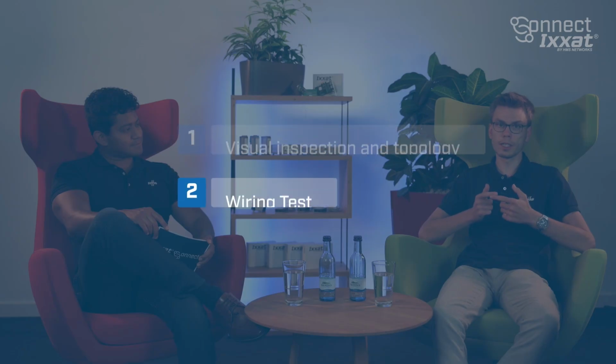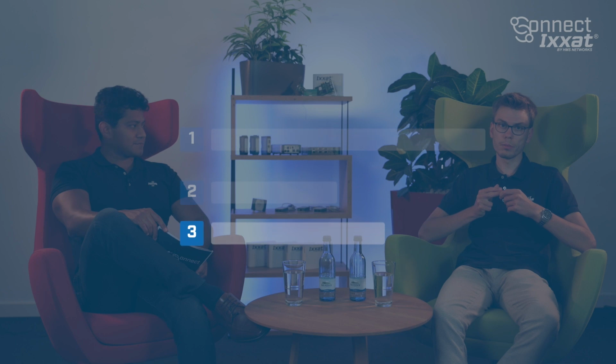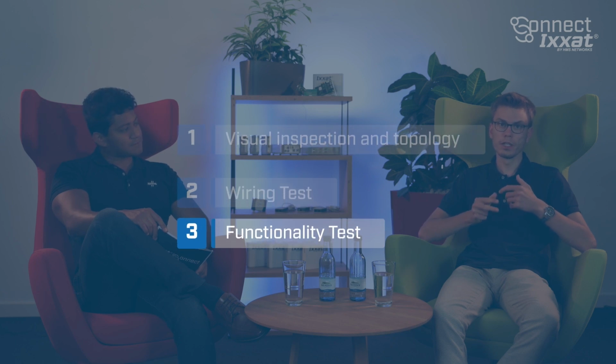Second, there's the wiring test. You should check the wiring, including the topology, cable integrity, and termination, to ensure that everything is connected properly and according to the specification. The next step, number 3, is a functional test. There you check the system's functionality to see if the problem is reproducible, sporadic, periodic, or a permanent problem.